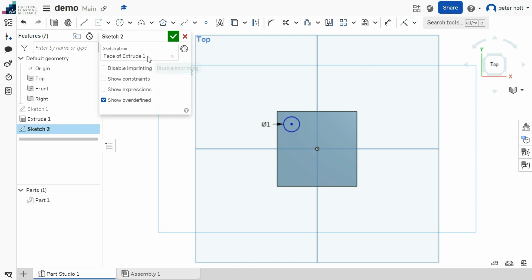So now I can pick things up in my sketch. I've still got my sketch open, but now I can pick things up. Now if I pick this up, it's going to think that I want to change the size, but because I've locked it to a size, it won't let me do anything. So clicking and dragging on that's not doing anything. If I click on the center circle, I should be able to move it. I'm not using a mouse at the moment, so bear with me a second. I'll see if it works with the touchpad. There we go. So I can move that over, and then I can position it wherever I want. So I can get it really accurately placed onto that origin point. So I'm happy with it.